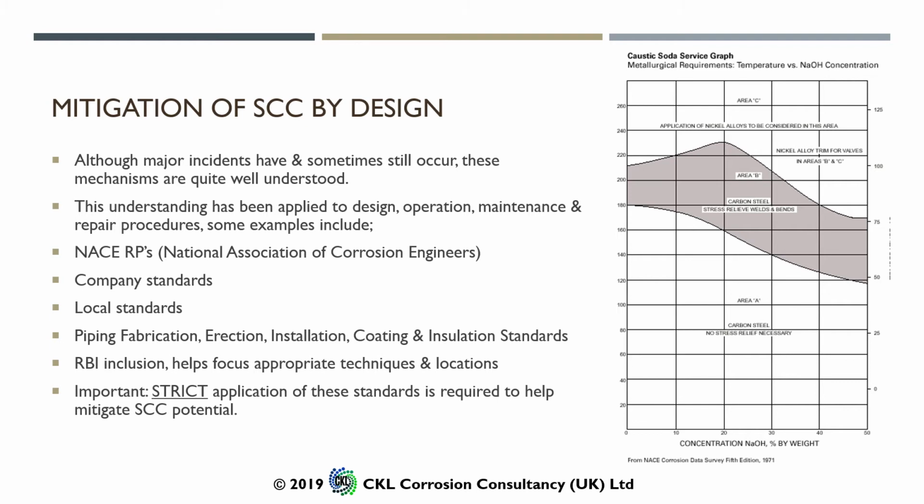So the major oil refining companies have their own company standards within which they will specify post-weld heat treatment requirements, considerations for items entering caustic service, amine service. So there'll be company standards as well, which will document the requirements to avoid these sorts of mechanisms.